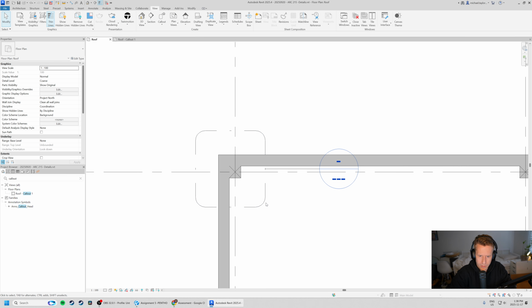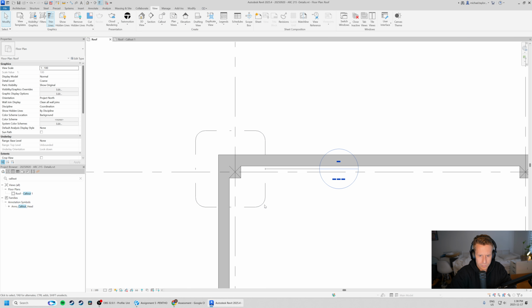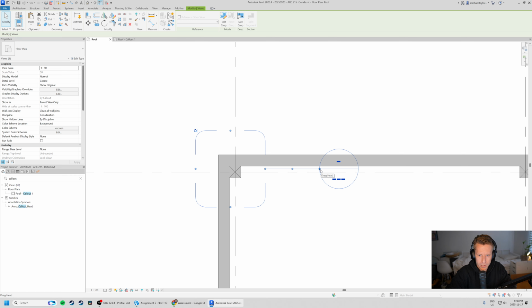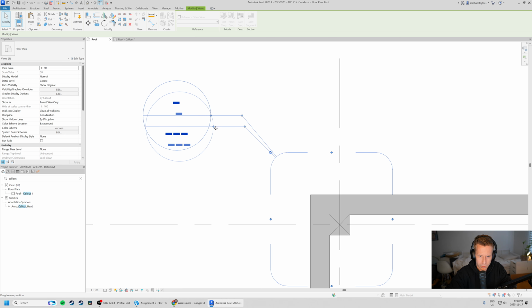So if I click on this, I've got to click on the view itself. Just single click. And then what I can do is actually drag the head. I'm going to hover over here and take this, and maybe I put it up here, maybe I put it down here, clicking and holding and dragging the mouse where I want it. Some people like them like this. And then to get a 45 degree angle in here, something like this. You can see how Revit doesn't do exactly what you want, but it's close.